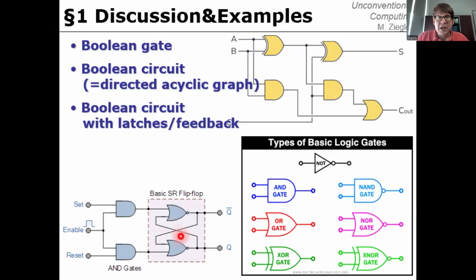And I mentioned and want to say it again, this is a pretty complex way of storing 1 bit, right? It requires 4 gates, and each gate typically in turn is combined from at least 2 transistors. So that's like 8 transistors with, oh, there's also negators here, right? So that's roughly 10 transistors in order to store 1 bit statically. And that's a benefit. When there's no enable signal coming, then it will store the bit indefinitely as long as the power supply is running.